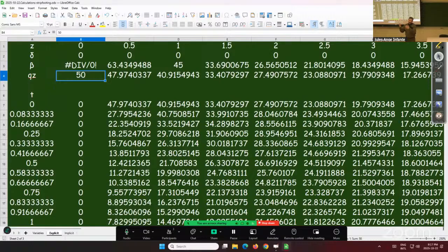So lab tests done on clay like this will give you a false sense of lower hydraulic conductivity than what is applicable in the field, because when you have little seams, and this is where doing these simulations can help you figure out, once you start doing 2D and 3D, it will let you take that into account.